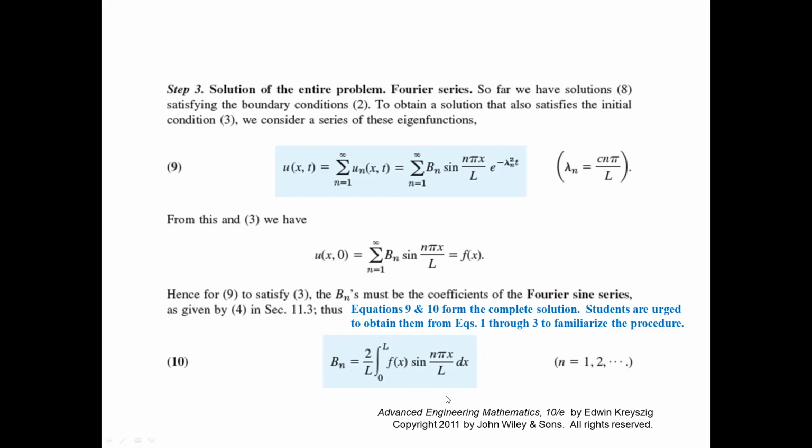So the solution of the heat conduction equation, the one-dimensional heat conduction equation, is a Fourier series representation with the coefficient obtained in this way. And then for many homework problems, we are asked to plug in F, so we get a coefficient, and we can see the temperature distribution by using this equation.